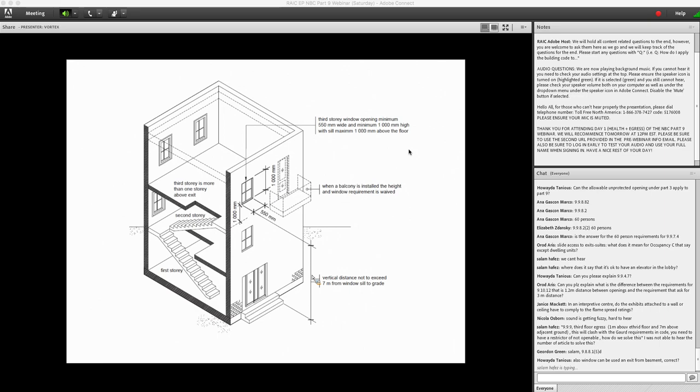And then your entire building can still be classified as residential. Typically, when you have an assembly occupancy, it may be considered as subsidiary to the residential occupancy, so it wouldn't make much difference. And it's not a major occupancy as well.